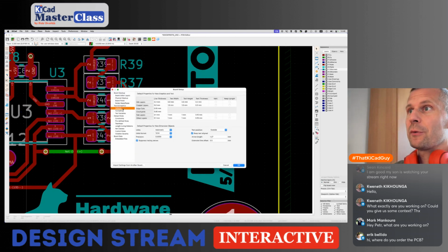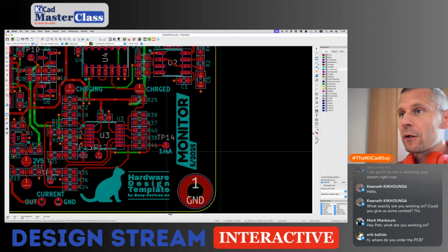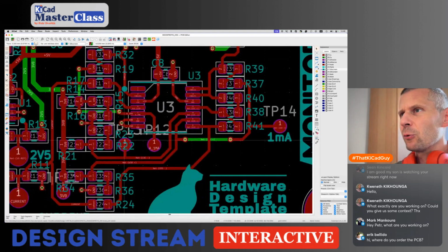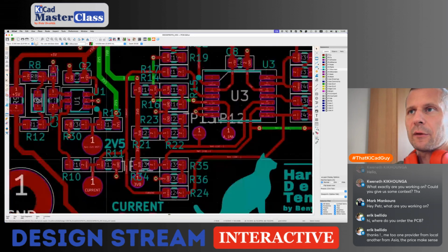There is a board setup, text and graphics default section, and when you edit the silk screen or any other layer numbers, the default values will be changed. So for instance, when you are placing labels near the test points, you can make the text bolder. If you are placing general text, you can make it thinner or narrower. It's up to you. So you save your time because you don't have to change the label properties manually.